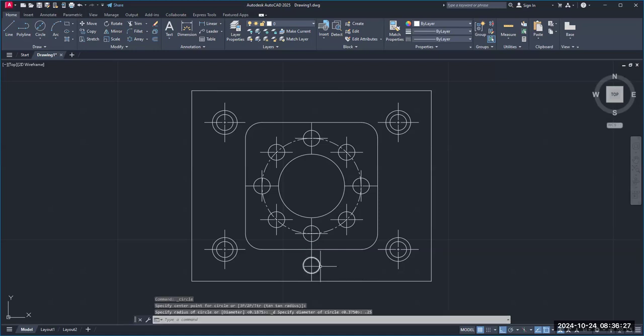Now, something you may not be aware of that you're going to be doing in the shop, depending on if you've already started your thread gauge: each one of your holes that you have to tap has a tap drill. You have to tap drill first, okay? You have to use your tap drill first.